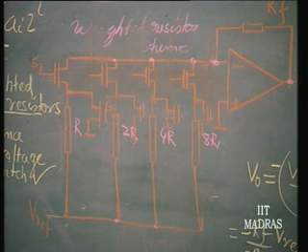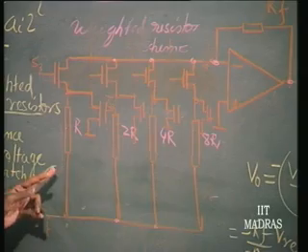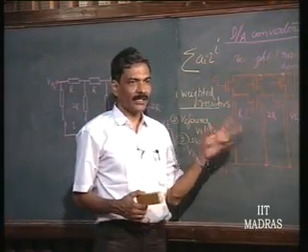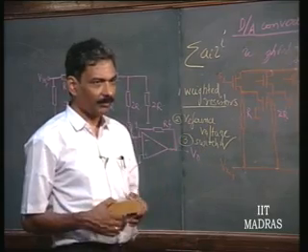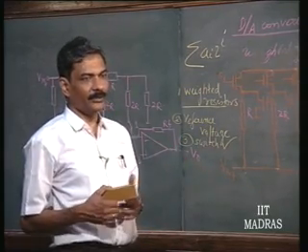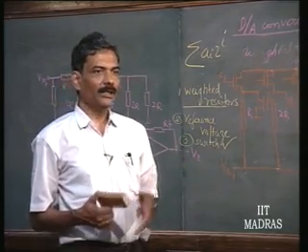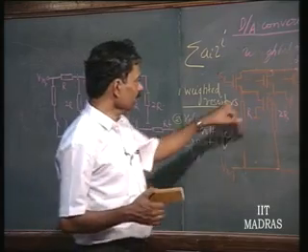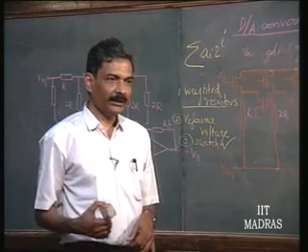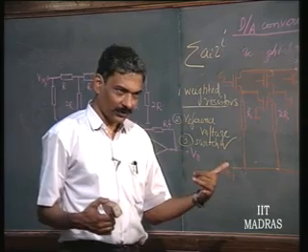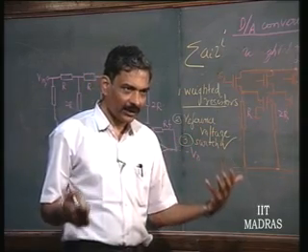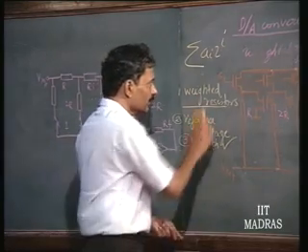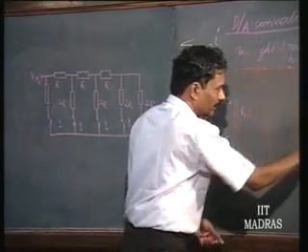Right. Now, I would like to normally avoid the switch resistance coming in series with the resistance, because this is again a random variation which is going to occur. Okay, it is going to cause serious problem. So, how do I really do current switching with the switch not coming in series with the resistance, but the switch coming in series with the current source. Okay. If you put the switch in series with the current source, then the switch resistance is not coming into the picture.